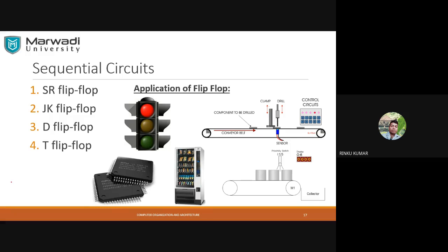No, sir. See, the clock signal, that will be this kind of signal, right? And that is continuously generated by the crystal. So if the circuit itself is, let us say, level triggered, that means all the sequential components will take a decision only when a certain level of the clock is reached.